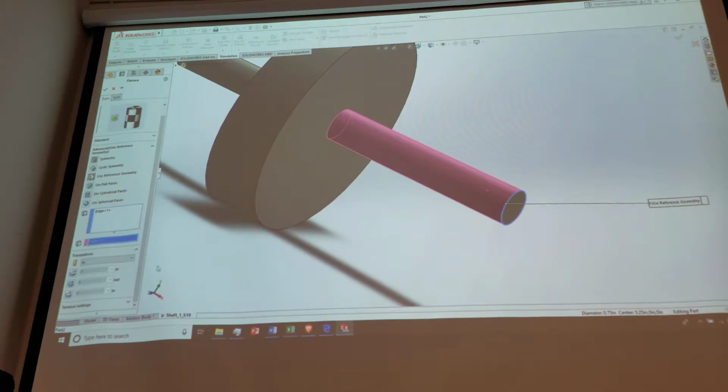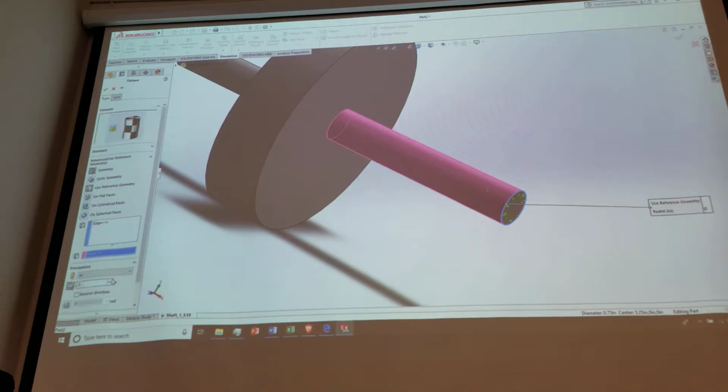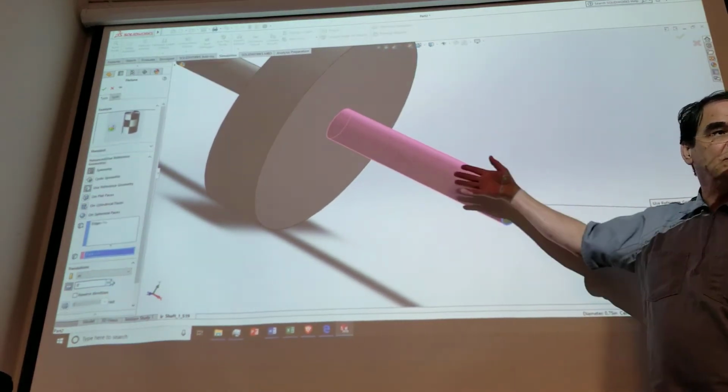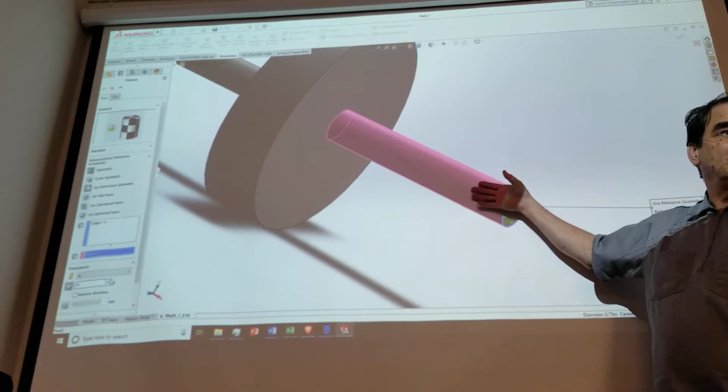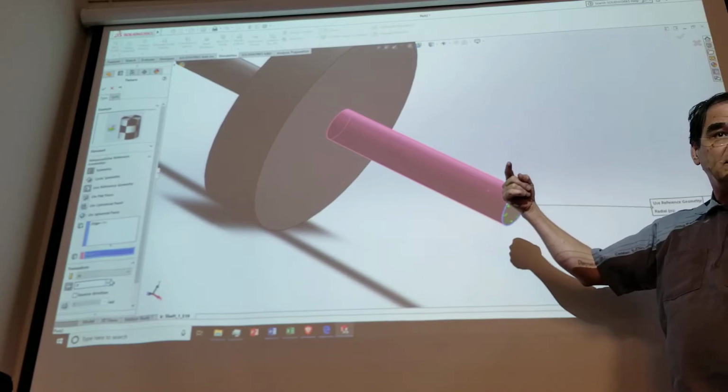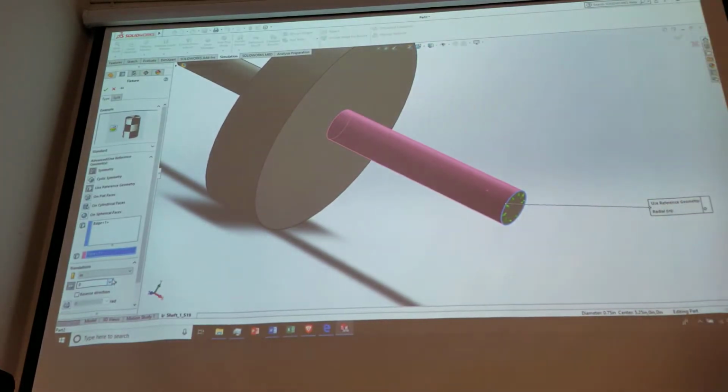So this one over here, I just want to stop the axial direction, right? On this end here, all I want to do is stop it from moving in these directions. It's allowed to move this way. It's allowed to twist. It's not allowed to move in the radial direction, because then it would take off into space somewhere, right? Okay? Does that make some sense? Sort of see why we're doing it here? Okay, that's like a simple support, right?